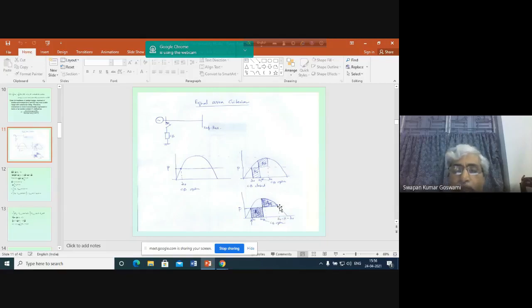Here at this point speed is again the synchronous speed, and as the speed is again the synchronous speed, you can say that just a moment after this point is reached, again the speed will become less than synchronous because the generator was retarding in this period. So again the speed will be below synchronous. As the speed is below synchronous, the generator will now move backward. Delta will decrease. So this indicates that the second swing has started. By observing the first swing and by applying the equilibrium criterion, we can say whether the system will be stable or not.